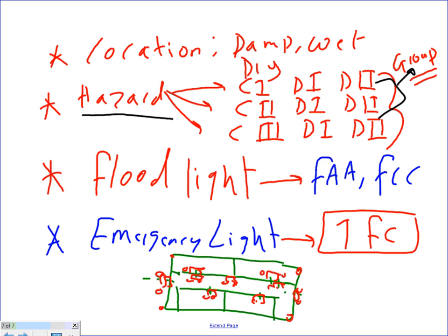So for the time being, when you put a fixture, be very aware of: is the place hazardous, is it a classified location? For example, I think this place is a classified location because Chad's voice is a hazard. Oops, they say that. So do we have a flammable gas here or liquid? No. Combustible dust? No. We have dust, but not combustible dust. Do we have flammable combustible dust fibers? No. So it's a non-classified location. All I have to pay attention to is a dry location fixture, done.